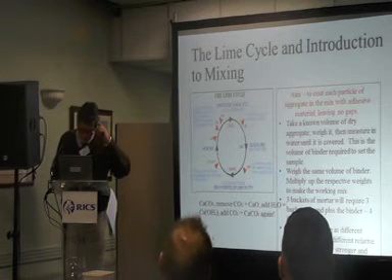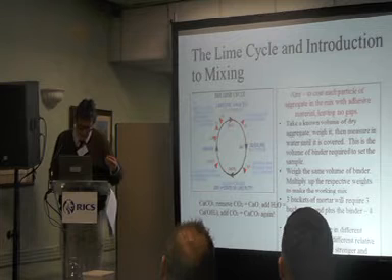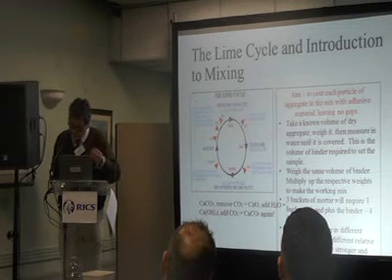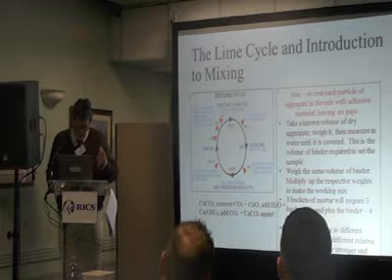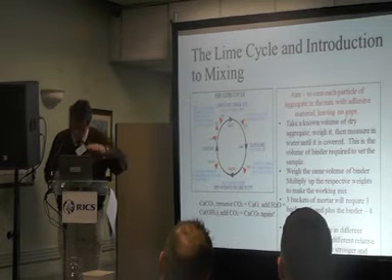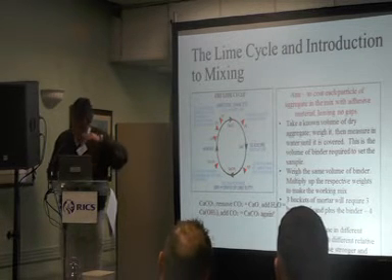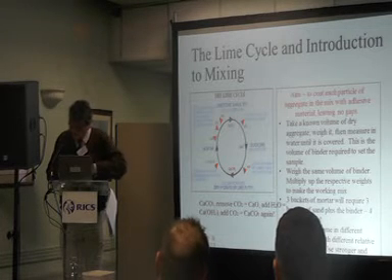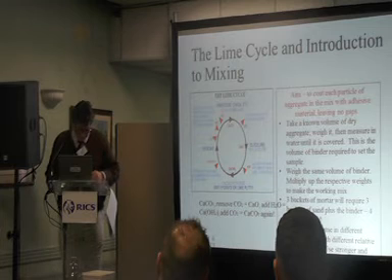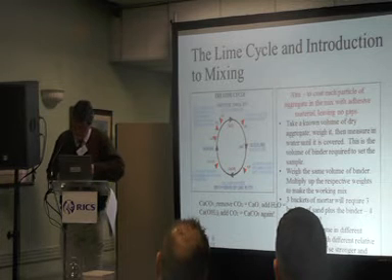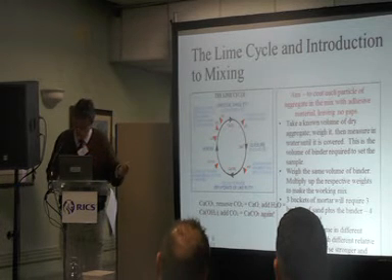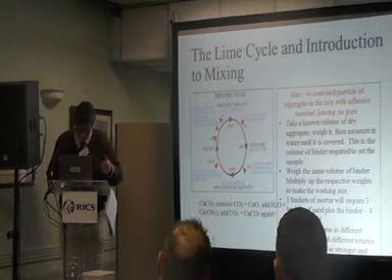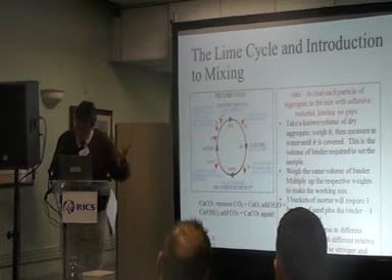So for mixing, your aim is to coat each particle of aggregate in your mix with adhesive material, leaving no gaps. So if you take a known volume of dry aggregate, you weigh it and then measure in water until it's covered, that's the amount of binder you're going to need. That volume of water you've put in is the volume you're going to need of binder. Now if you weigh that volume of binder, you know your ratio between your dry aggregate and your binder. So it's very simple to do, and you multiply it up to make a working mix.